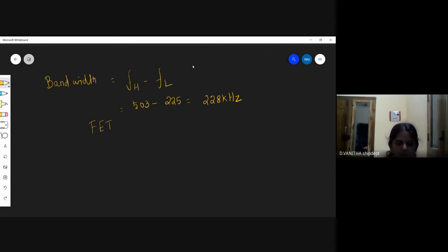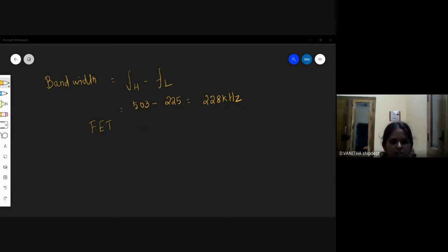Here the output of the transistor's emitter is always in phase with the output of the collector, so that the feedback signal is always positive in the case of the Hartley oscillator. The oscillating frequency, which is a sine wave voltage, is determined by the resonance frequency of the tank circuit. So these are some points about Hartley oscillators, their construction and working explained here.